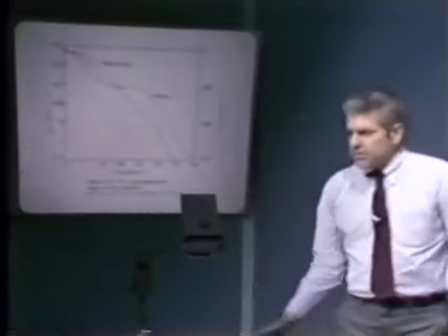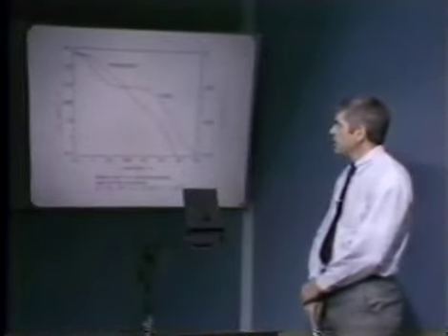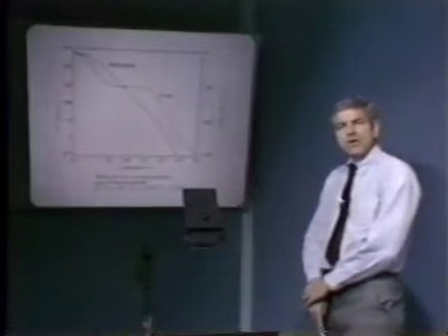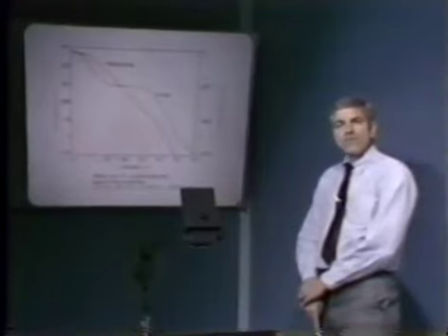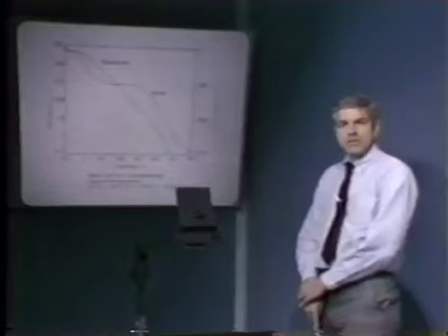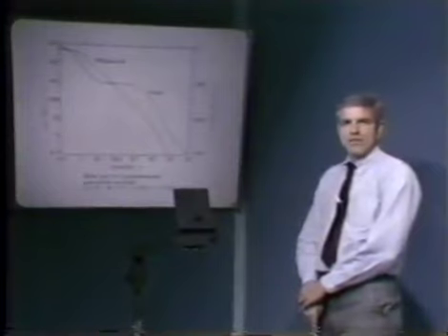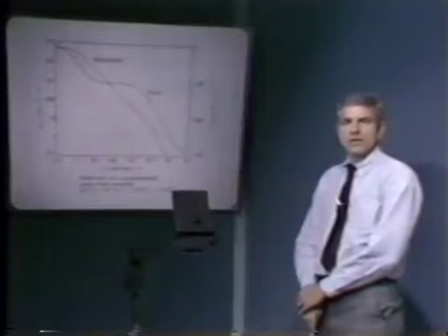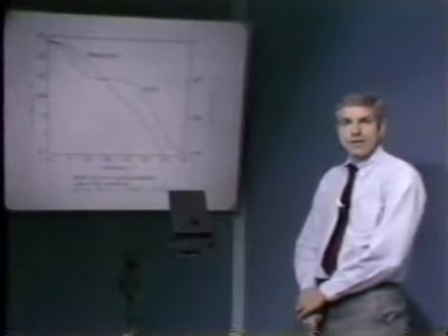And our reasoning goes something as follows. If we have the zero of the lag network located about a factor of 10 below our compensated crossover frequency, the residual negative phase shift associated with the lag network will be something on the order of 5 degrees. If the pole were very far below the zero, we'd get 5.7 degrees of residual negative phase shift. Assuming the pole is somewhat closer to the zero, we get a residual negative phase shift on the order of 5 degrees. So if we follow this rule of thumb to start our design process, we anticipate roughly 5 degrees of residual negative phase shift associated with the lag type transfer function.